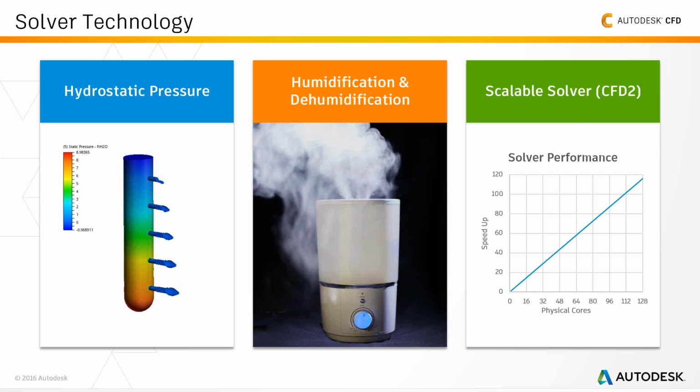This image you're seeing is a pretty good depiction of what we're talking about. Obviously, the further down in depth you go for dense fluids, so mostly used water, you'll have a higher pressure, and therefore this is a vertical manifold. In past versions of our software, if you just wanted to let gravity take effect and actually have the distribution be done properly, you would have to enable basically free surface, and that would enable the hydrostatic pressure option.